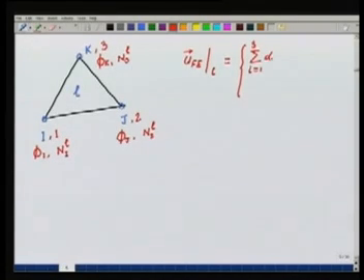Alpha I of the element L, N I of the element. Sorry, it won't be alpha I, it will be alpha, we will have to do the appropriate thing, alpha 2I minus 1 of the element L. Similarly, the second component of the displacement, or the V component, will be alpha 2I of the element L, Ni of the element L.